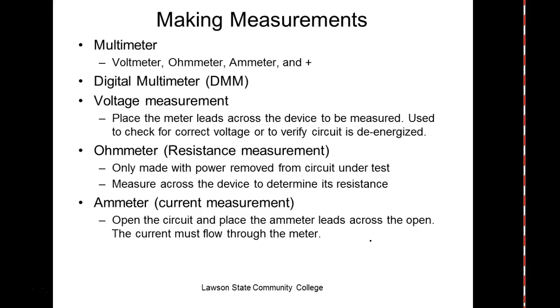The only problem is, to get that, we have to induce it, so we have to use AC. So these things usually only work in an AC circuit. We do have some that measure DC, but they use a special sensor called a Hall effect sensor, which we'll talk about when you take the sensors class. I think the sensors class is required in both programs.